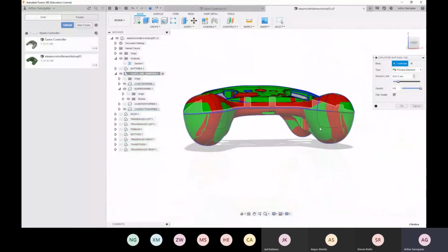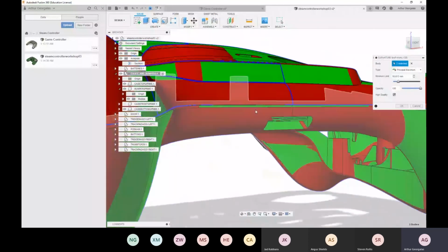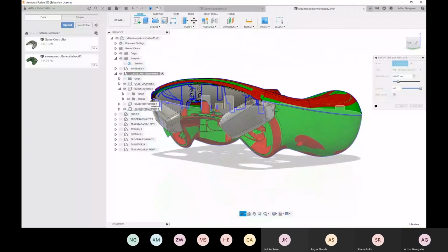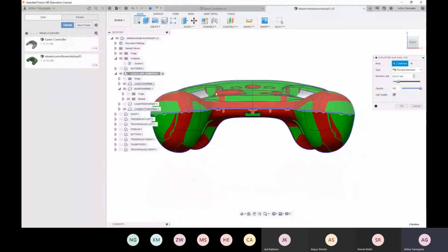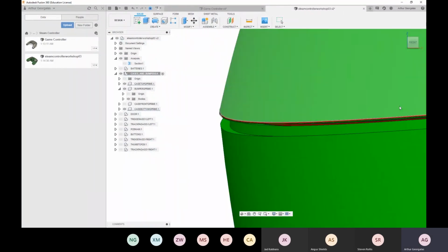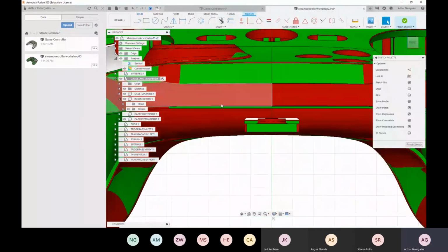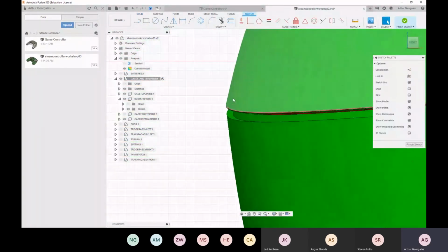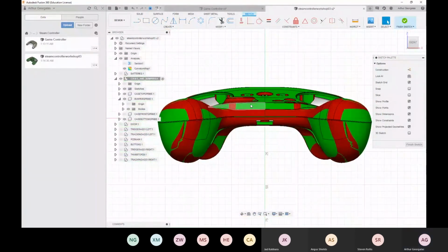And the front is generally just split in the middle because it's a tighter area. You need a bit of surface area on both sides. But this is how most controllers will go. And another thing that's very important when it comes to splitting is looking at how these surfaces meet up. So this is what's called draft or draft angle. And what we need to know is when you've got something that goes into an injection mold, it needs to be able to go in and out of a mold, right?